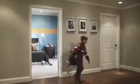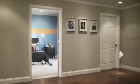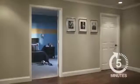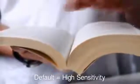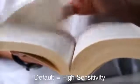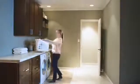You can adjust your sensor to automatically turn the lights off depending on the amount of motion it senses in the room. The default setting is high sensitivity, which detects fine motion such as turning a page, so the lights won't turn off when you're reading. Low sensitivity detects only larger motion, such as walking across the room.